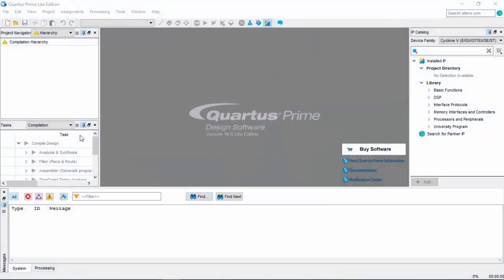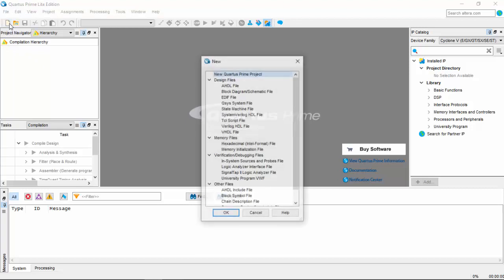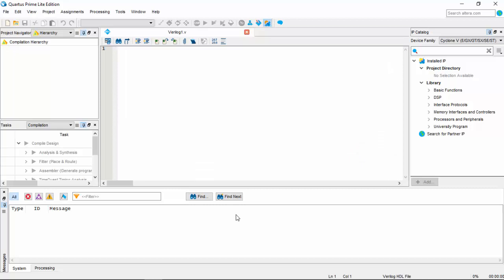To start coding on Quartus 2 Verilog, we first start with a blank document and we choose Verilog HDL file. Click OK. In this first exercise, we just want to fabricate a single gate, and we want to fabricate a different gate each time. So we are not going to name this module to a specific gate name. Instead, we are going to call it just a gate. So we type module a gate.